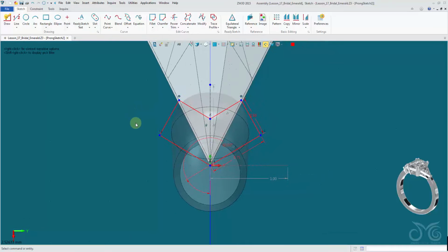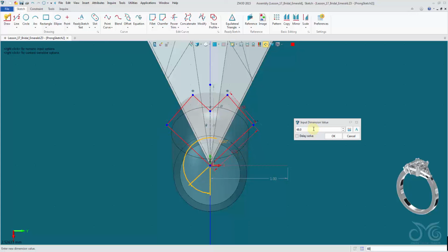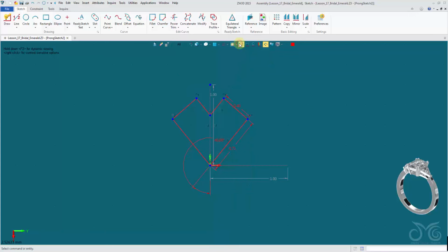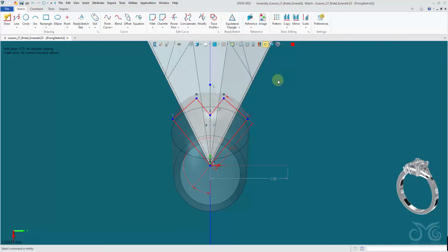Okay, I'm going to want to change some parameters here so that we can align our prong with the shape of the gemstone better. I'll drop down this angle. Okay, I'm not going to go further than 40 because we're losing our V shape up here. If we go any further, we lose the shape. Maybe I'll take my width down slightly to 0.4. Okay, we don't have the offset parameter here, so I'll just perform a move back in the 3D environment.